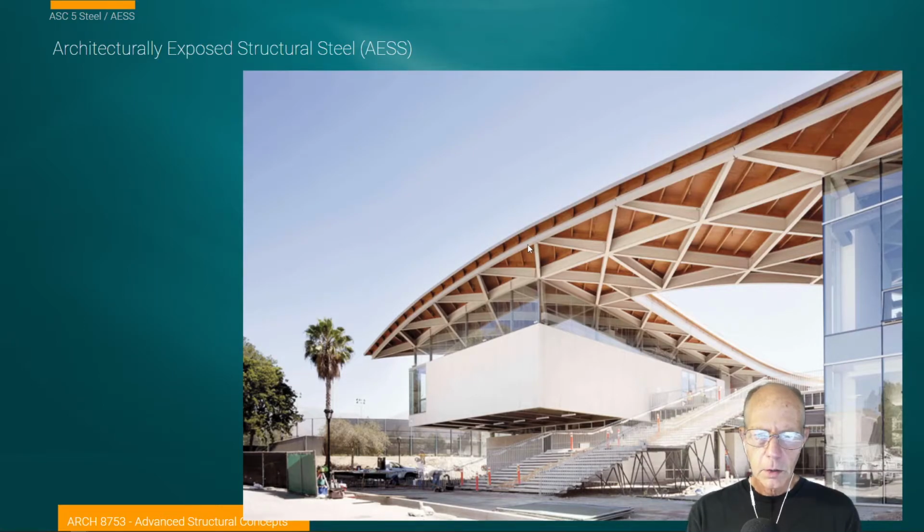And in a way that makes sense because on the interior beams, the tributary load is coming to both sides of those beams. When we're the last element to support a floor system or a roof system, the loads are much lower because we're only taking the tributary loads from half of that section. So therefore, they were able to thin that down. And the associated cantilevered beams that are supporting that final beam are actually tapering. So you can see how they get smaller here. So there's a lot of really attractive things visually happening here to make the outside edge of this appear to be thinner and more lightweight.